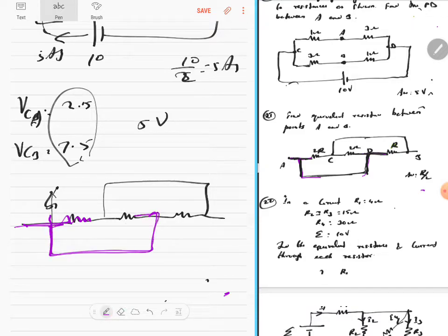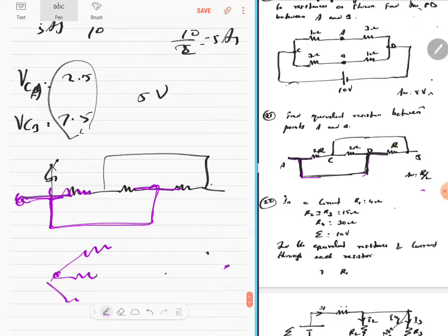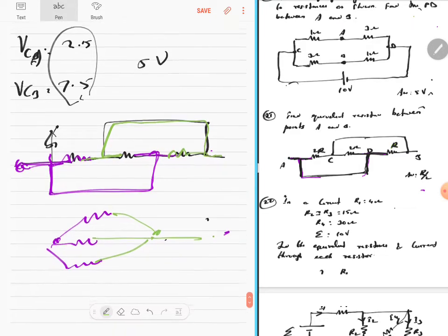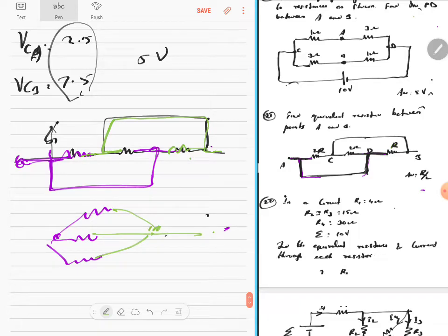So one end is connected to 3 resistors. One end itself is connected to 3 different resistors. Let's take the other end. It goes here and here. So this end is also connected to 3 different resistors. So therefore it becomes parallel. This is nothing but this circuit. Are you clear? That's all. And then it's a question of this being 2R, 2R, 2R: 1 by 2R plus 1 by 2R plus 1 by 2R, you get the answer, take the reciprocal. So let's go to the next question.